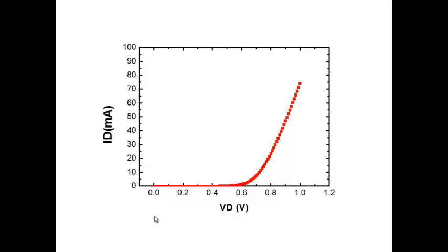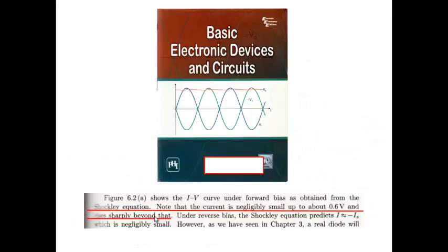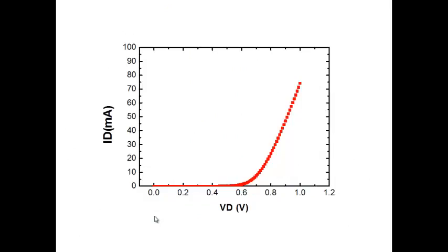What is really happening is that we are just approximating. There is no cut-in voltage inside the diode. We're just taking an exponential and we approximate it for convenience, for simplicity, and whatever is the voltage at which we approximate, we call it cut-in voltage here. A good way of removing this misconception is if I show you a plot like this, right?